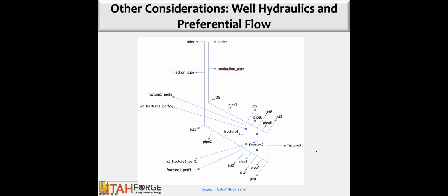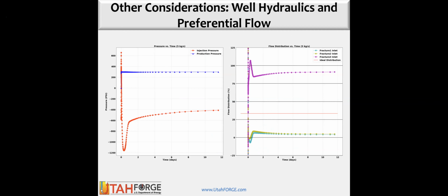I should also mention that there are practical limitations on the size of the pump we could use for an outflow system. So our design right now is looking at essentially a pump that can make about 250 gallons a minute, which, depending on the fluid temperature, is about 13 to maybe 15 or 16 kilograms per second. And I apologize to all you oil patch guys, I don't have that in barrels per minute, but it's not all that many barrels.